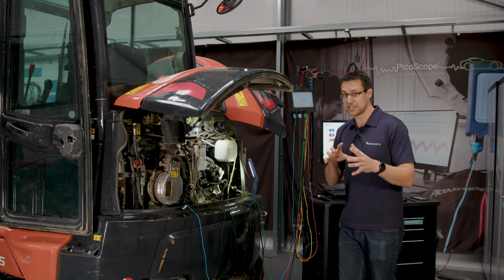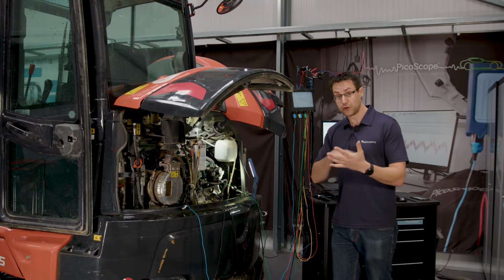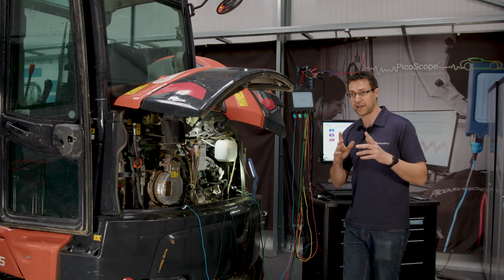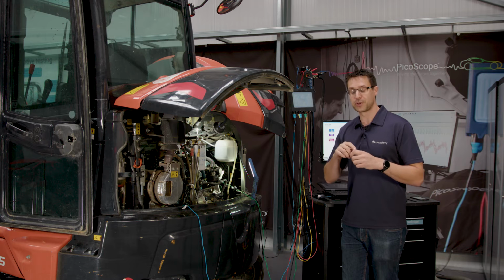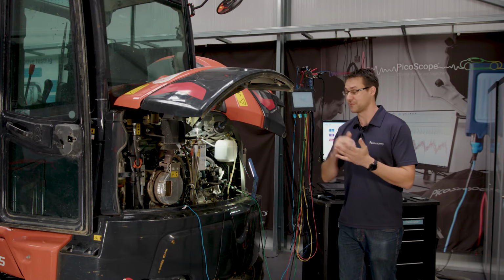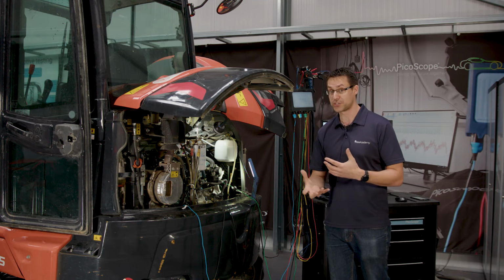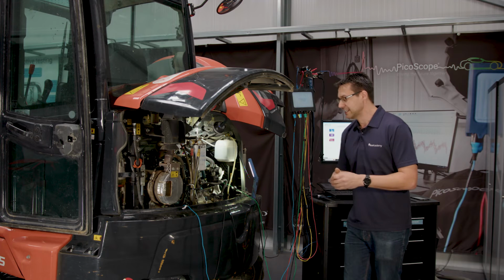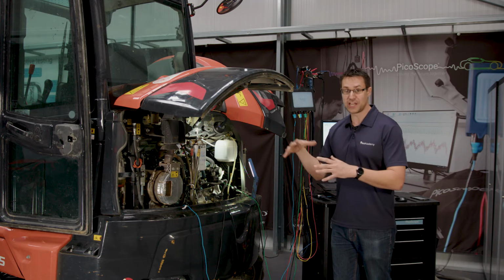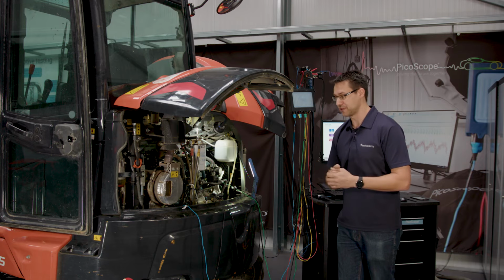A couple of things to consider is obviously the pump and how many lobes are on the high pressure pump. So we'll obviously get a momentary increase in pressure because the piston in the pump has been forced up, supplying the rail with more pressure and more fuel, more flow. And then obviously how that changes in relation to after each injection event.